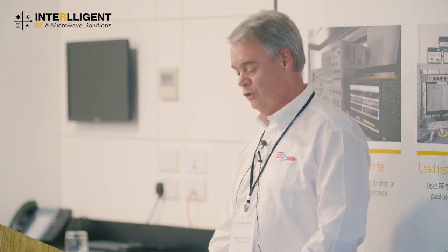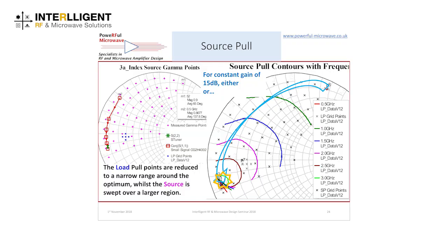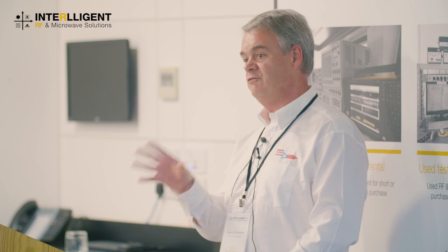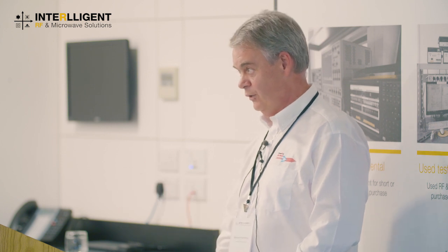But because we plotted the contours, we might have noticed one other point. Down here at the bottom, all of these circles converge. So if we put our impedance down here at this point, and that is a much easier matching problem to deal with, we could get a flatter gain that way. So you can actually graphically visualize where the optimum points are.